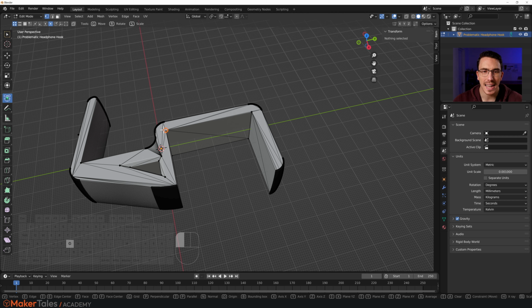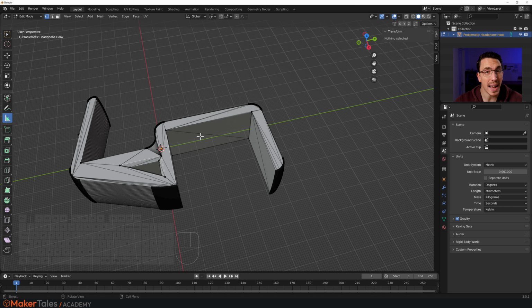Or I want to introduce to you a new tool, which is the measure tool right here. Now it is a little bit weird though. So if I click this tool, it's now on. Now it doesn't snap. We have to actually turn on snapping by holding down Control, and it has its own snapping style. It's different and independent to this one. So I'm going to click and drag from one vertex to another, and I can see here that it's 50 millimeters. I can click and drag down here and it makes another one. It deselects this one, but here's a little bit of a caveat. If you click out of this tool, they disappear. So just be aware of that.